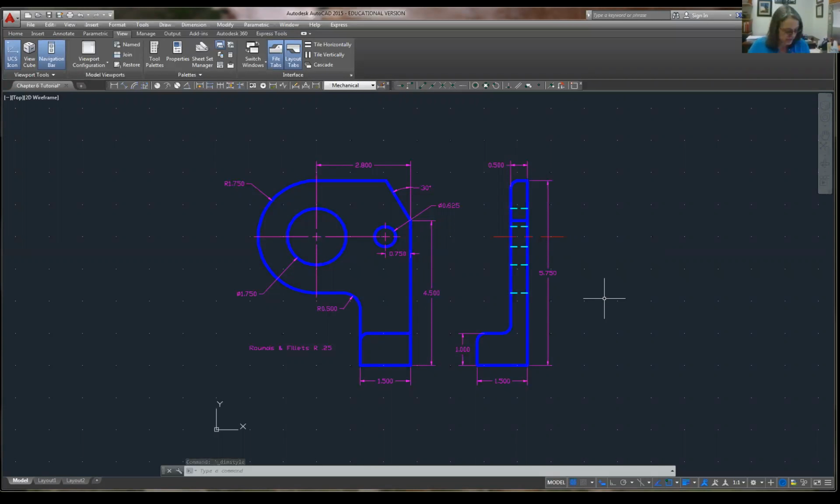Okay, so let's start with the 1 3/4 inch hole. We're going to have a shaft run through this hole with moderate speed and fairly heavy journal pressure. We're going to have a fit class of RC6. So if we go to the appendix in the back of the book, we can see that means that our minimum size hole will be our 1.75, and our largest size hole will be plus 2.5 thousandths above that.